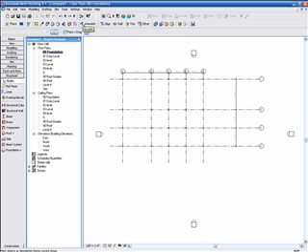Alright, the next thing we're going to do here is, because we've added some elements, which are the structural columns, they're actually 3D. We have been working in a 2D format most of the time, and right now we're going to start showing the strength of parametrics. So with that, we're going to create a 3D perspective view of the building. So we're going to go to our project browser, under floor plans, and we want to be on level or entry 1.